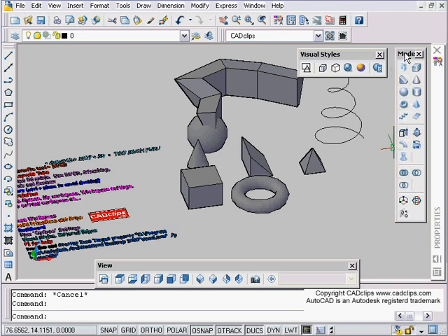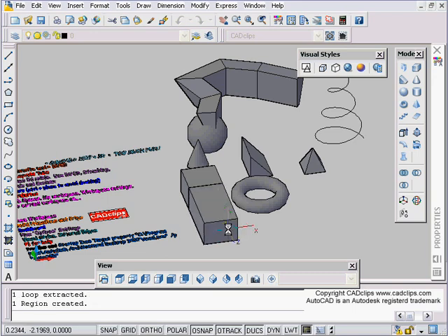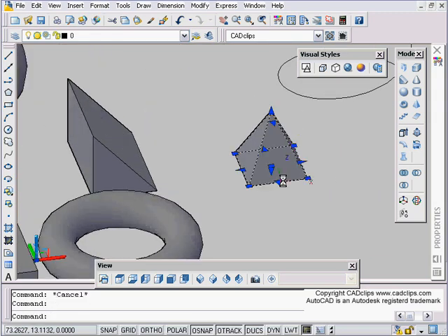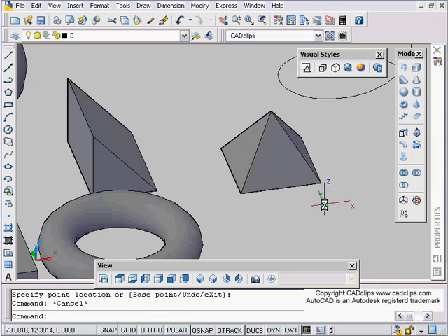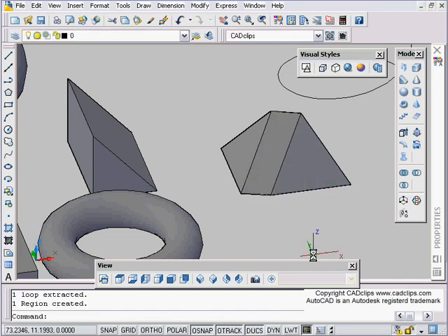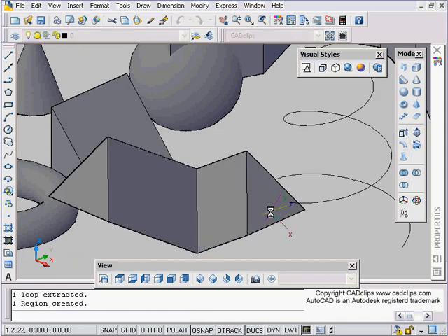Again, this is the modeling toolbar. Right click, modeling. Okay, we're going to get into some more of these with our extrude and push pull and stuff like that, where you can go in and pull faces off and all kinds of great stuff like that. Push, pull, pick on here, pull that face out. Once you've done that push pull, you'll notice you'll lose your grips. Okay, I can go down to here and pick on this object, and I can grip it and do all kinds of great stuff with it. Once I go in here and use my push pull, pick that face, I can pull that face off, which is really nice. Okay, same as I can go over to here, pull this face off.